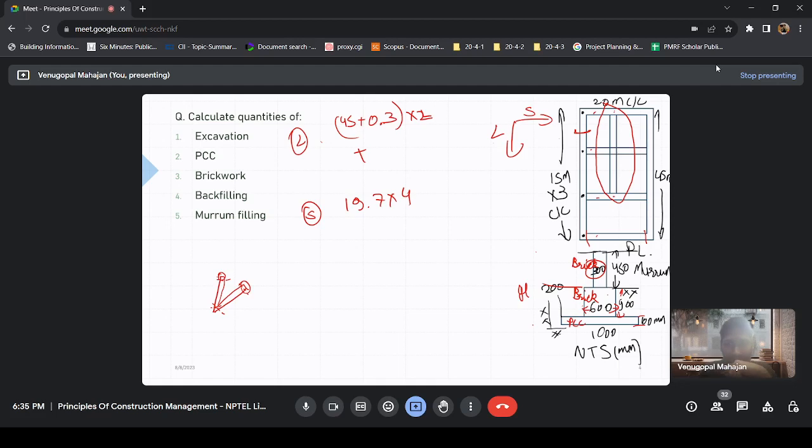Sir, we will take the total length in the y-axis, and we can subtract one full length of the short wall in the x-axis. Oh, one full length of short wall or one full width? One full width, sorry. Okay, so center to center would give you this, but if you just subtract one full width, you would be coming to this only. Still, there is a large overlap here.